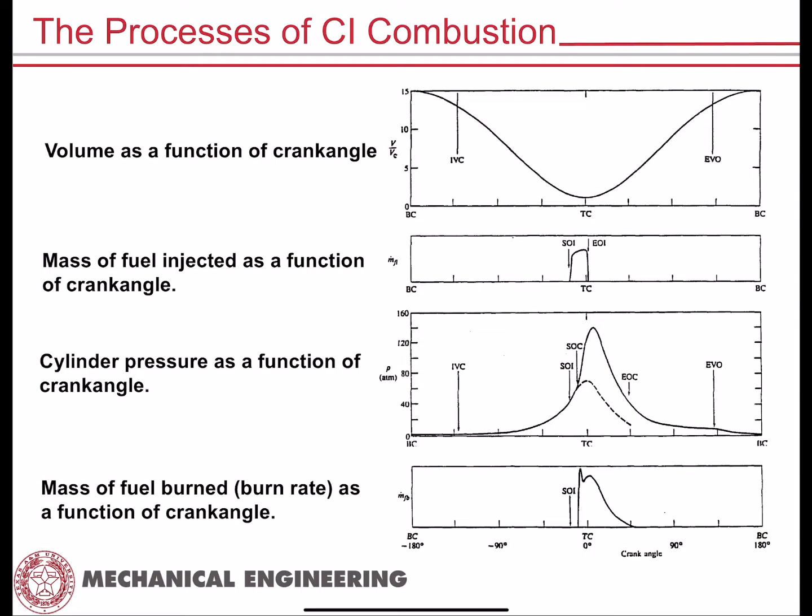There's going to be a little bit of overlap here with what we've already talked about with spark ignition combustion, but this will certainly look familiar, this curve here, right? This is the volume versus the engine crank angle. TC here, of course, is top dead center, and BC is bottom center. IVC, intake valve closure, EVO, exhaust valve opening. You remember all these good details.